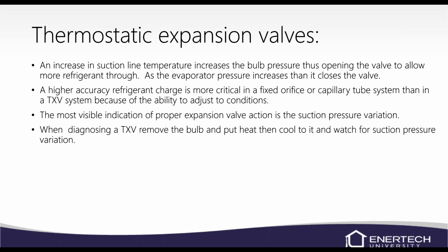Obviously, with a cap tube or a piston, or a fixed orifice, you've got to have a higher accuracy of refrigerant charge. With a TXV, we can overcharge the system, and it's not really as big of a deal because it'll just store that refrigerant in the condenser. Now, we don't want it to run overly charged.